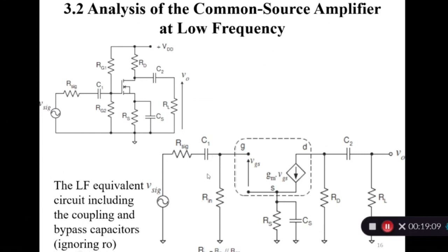So the frequency due to this section is a pole or a zero. How will you calculate it? For that purpose, I am telling you here, I think it is not in the lecture note. Take only this small section, V signal, R signal, C1, put here any voltage, for example V1, and look up. For this section, calculate the ratio of V1 divided by V signal, and then make the transfer function for this small section. Then find the poles and zeros.